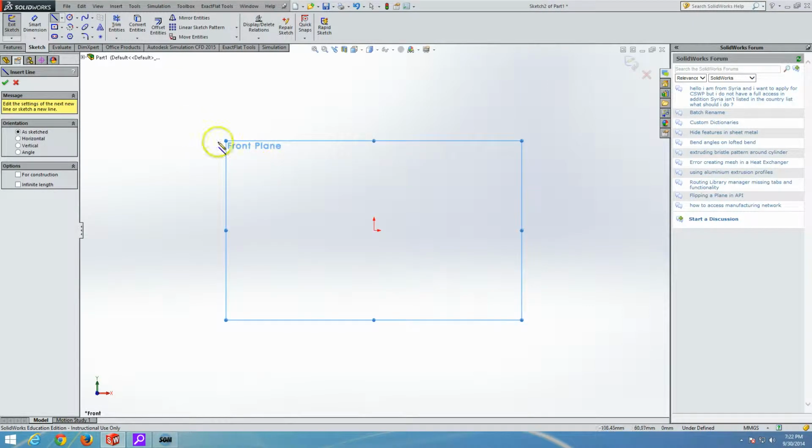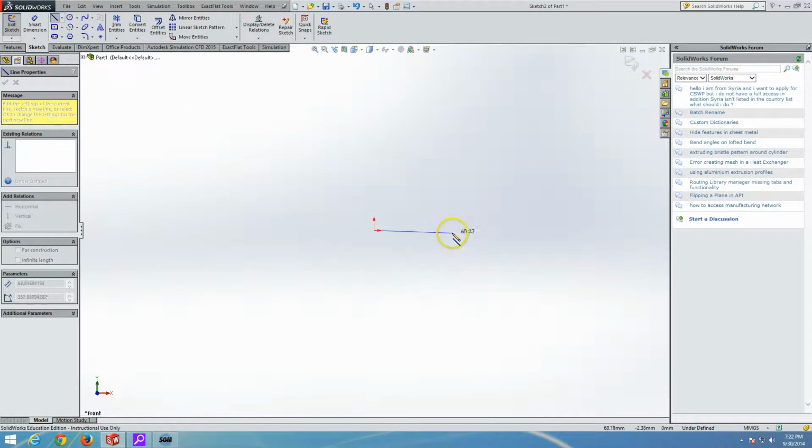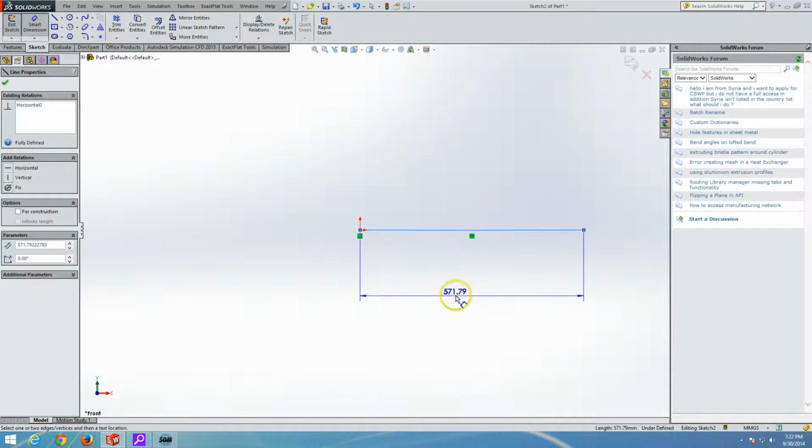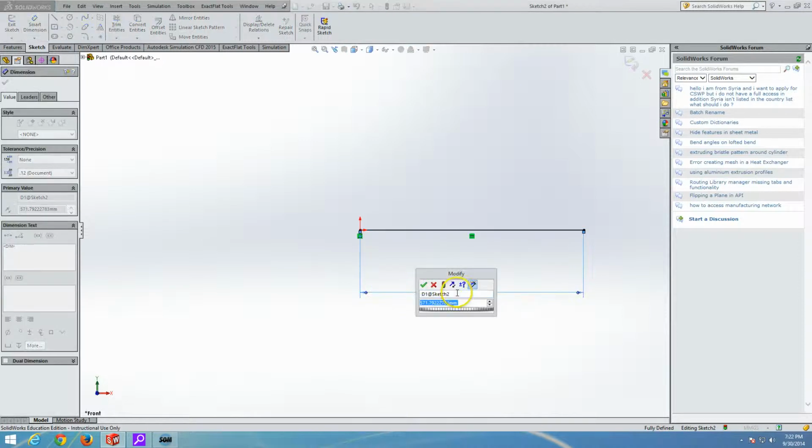Now we will set up the line. Everywhere where you place a load, or where the load starts and ends, the line structure needs to have a break point. So here we will type in 3000 millimeters.